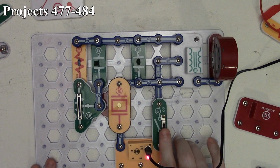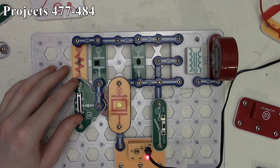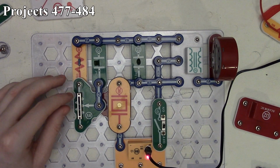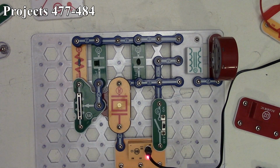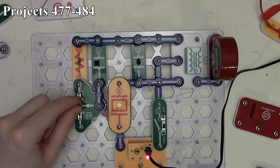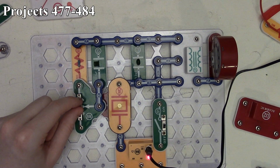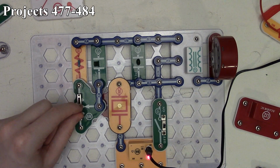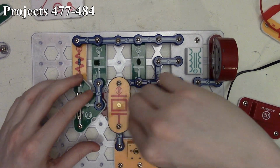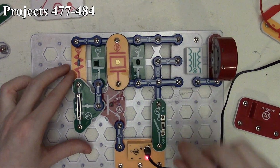We turn our circuit on. And now we just have our audio coming out of our whistle chip. But as you see, the whistle chip behaves differently than what the circuit did when we had the speaker there instead. So now let's move it in parallel with capacitor C2, see what happens there.